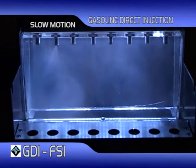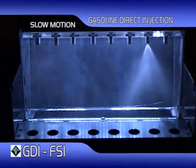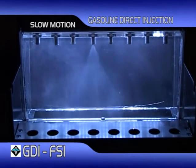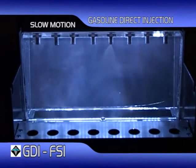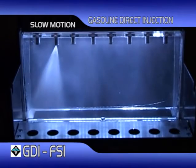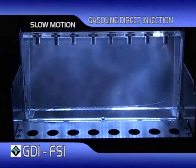Any permanent change in the fuel distribution or atomization is corrected by the long-term fuel trim. This fuel trim adjustment is not correcting the problem, it's adjusting the engine to compensate for it. All engines with direct injection have adaptive engine management systems. These systems are actually masking a deterioration in the injector's performance.